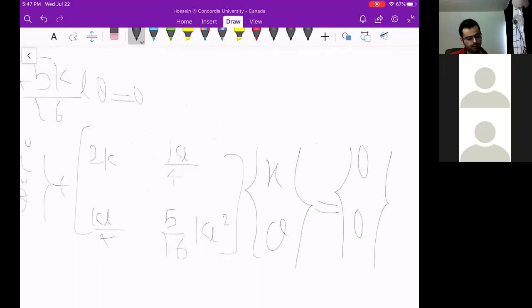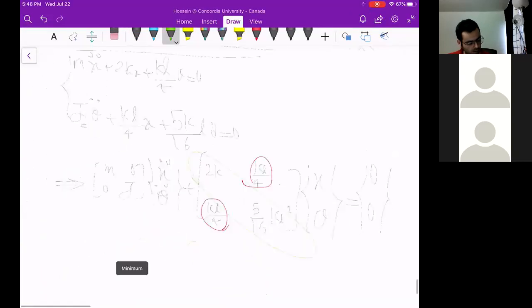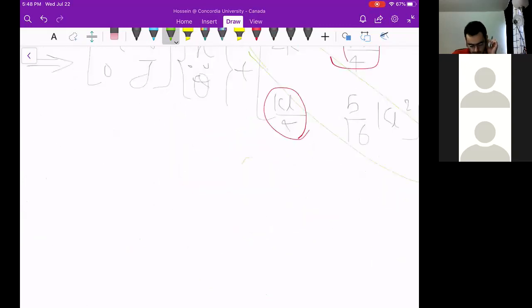So these are statically coupled because at each row we have x and theta. These two are always the same, just symmetric, and dynamically uncoupled. If one of the zeros were not zero, it was a number, we could say it is also dynamically coupled. It means at each row we would have x double dot and theta double dot. So dynamically uncoupled and statically coupled.